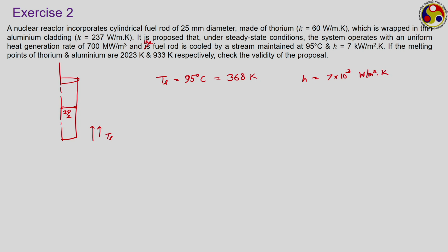Again there is a heat generation part. So, using heat generation, let us try to calculate the temperature T naught here and the surface temperature T s here. You already know the way to derive the expressions for this. For the moment you just neglect the cladding, just consider this is a cylinder having uniform volumetric heat generation. You have to calculate this temperature T naught and T s.